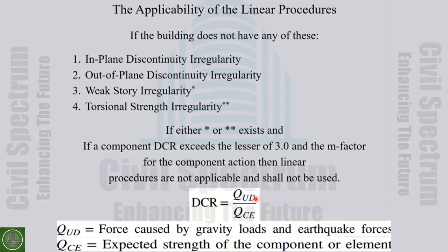Usually we say that in an earthquake, we design the building so that some locations get damaged, or act as a fuse, and that controls the amount of force that will transfer to the more brittle part of the building.